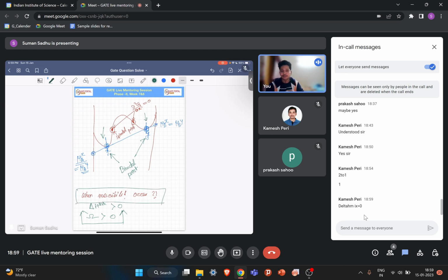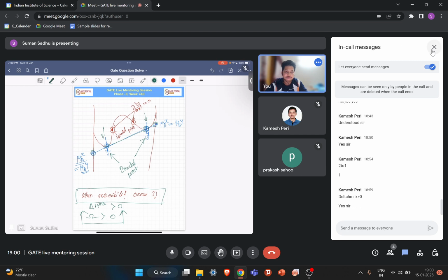And when will two phases be at equilibrium? When the chemical potential will be the same, right? Or when there is a common tangent between these two phases. If there is a common tangent between these two phases, then the chemical potential of these two phases will be similar. So then these two phases will be under equilibrium. Is it clear?